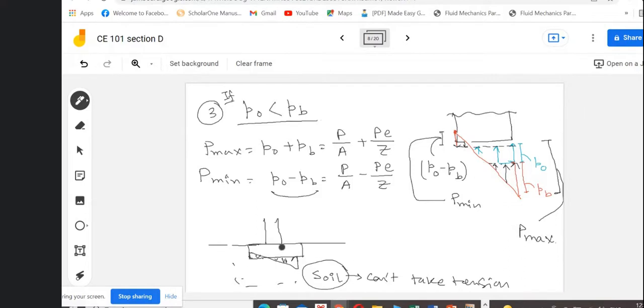So the civil engineer or the structural engineer or any soil engineer always tries to keep the stress which is coming due to the superstructure load from the top in the compressive zone. We always try to avoid this tension zone. So as an engineer, we want to find out the load in such a way that the stresses getting generated are in the compressive zone.